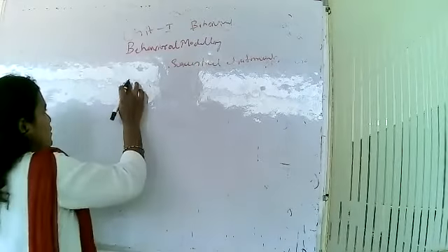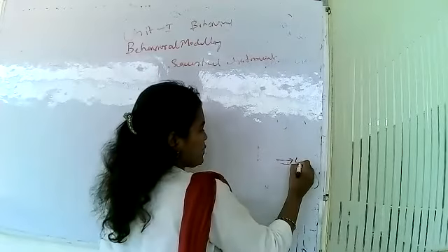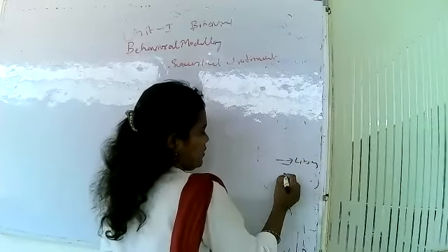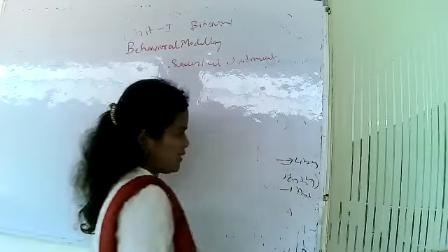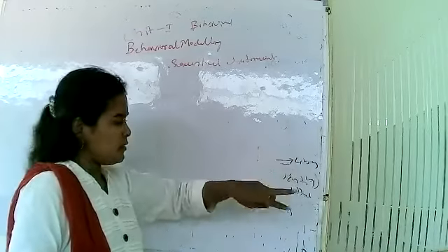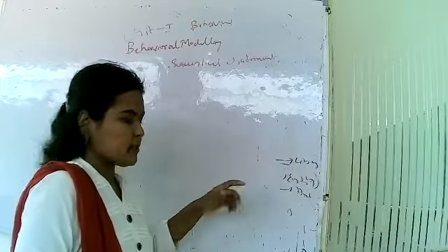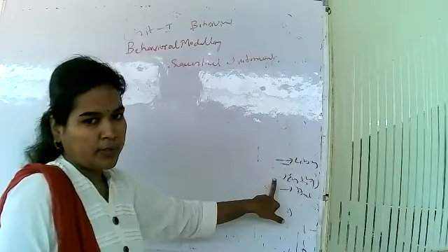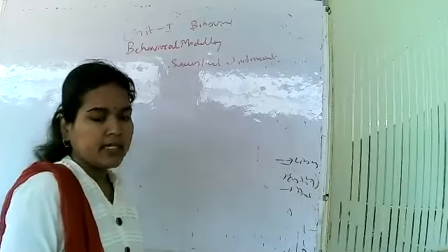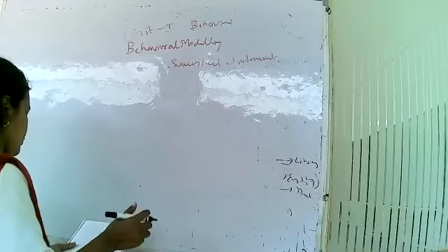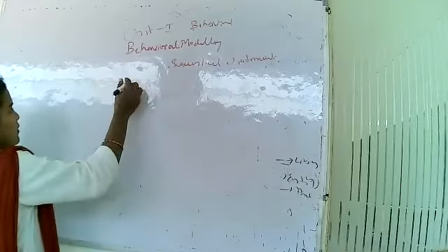I already told you there are three sections in VHDL programming: first library, second entity, third architecture. Library is two lines. Entity contains the inputs, outputs and selection lines. Architecture contains the design. So I start programming with the example of the D flip-flop.